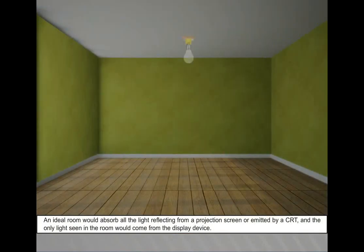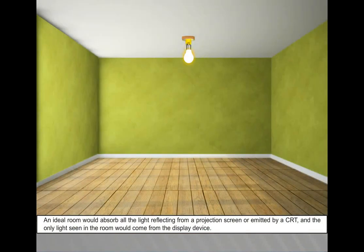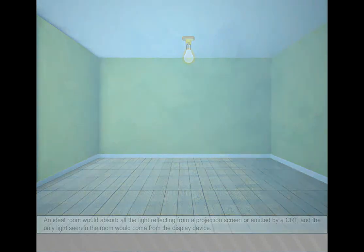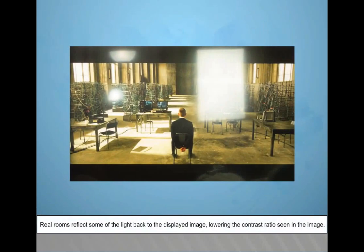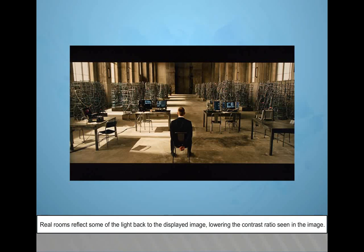An ideal room would absorb all the light reflecting from a projection screen or emitted by a CRT, and the only light in the room would come from the display device. With such a room, the contrast ratio of the image would be the same as the contrast ratio of the device. Real rooms reflect some of the light back to the displayed image, lowering the contrast ratio seen in the image.